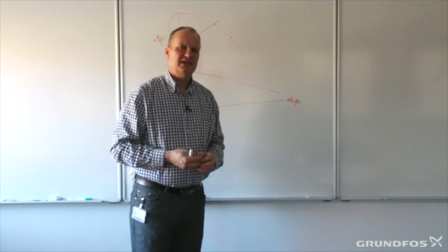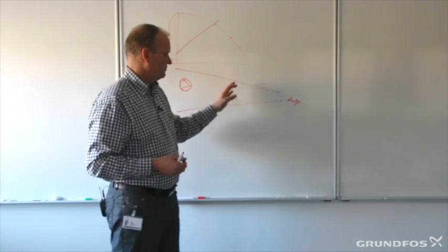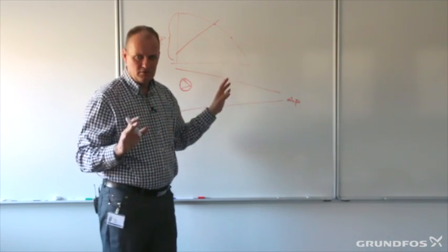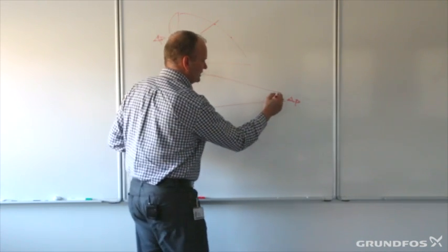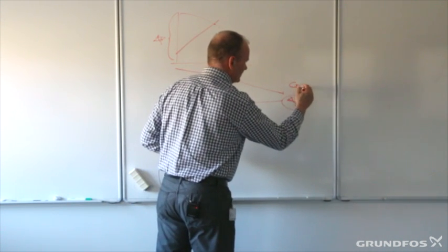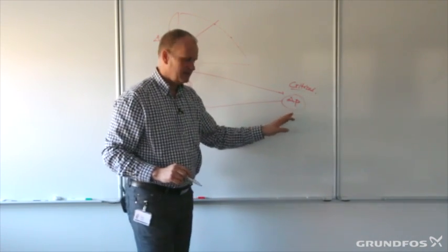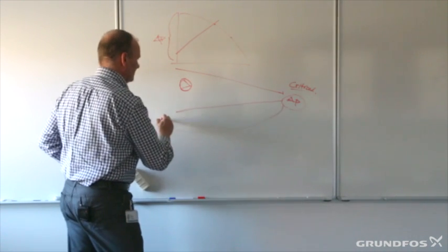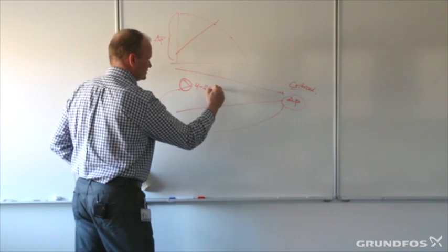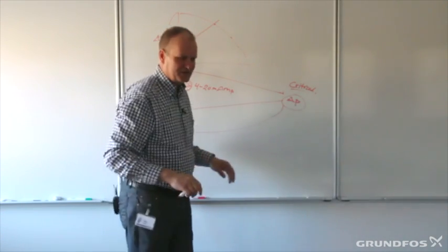And maybe he tells you that's 75 meters away from the pump, but we actually do have a SCADA system looking over the whole system. So we could monitor the delta P on the critical spot out here. What we could do with this signal is transmit it back to the pump, and typically that's 4 to 20 milliamps, but that's really not what I'm focusing on here.